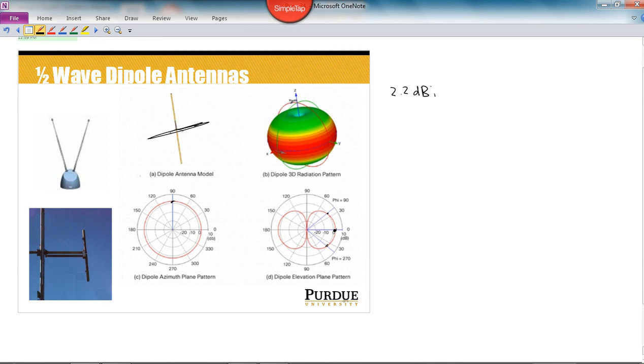Given these antenna patterns, you can see that the dipole antenna should be mounted so that it's vertically oriented with respect to the floor or ground. This results in the maximum energy radiating out into the intended coverage area, and the null in the middle of the pattern really won't affect us because, if we're doing it indoors, this is going to be pointed towards the ceiling and that will be pointed towards the floor. So it won't really affect our radiation.